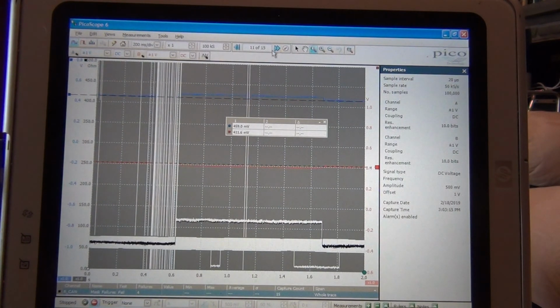And last but not least, on screen 11 we see that our resistance value suddenly got doubled, and that corresponds to one of the terminating resistors developing an open, and we see that the value goes from 60 to 120 ohms. So this is the end of the test. We were able to confirm how we see some of the faults in the CAN bus, and hopefully this will be useful for real-world diagnosis.